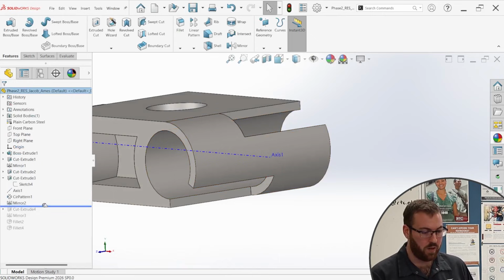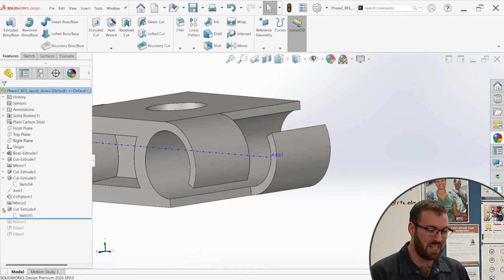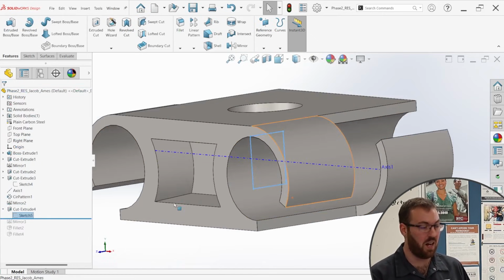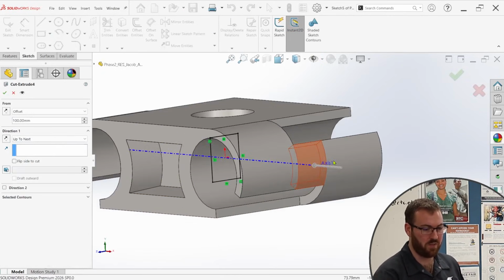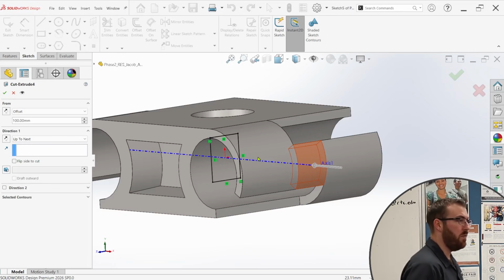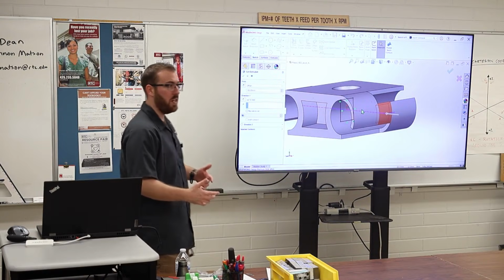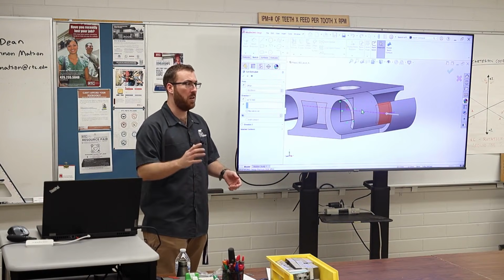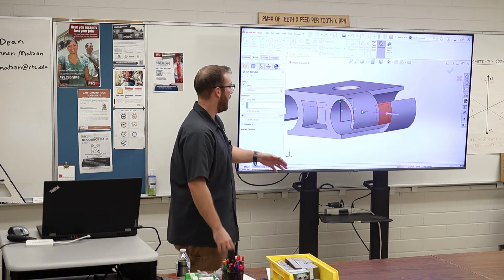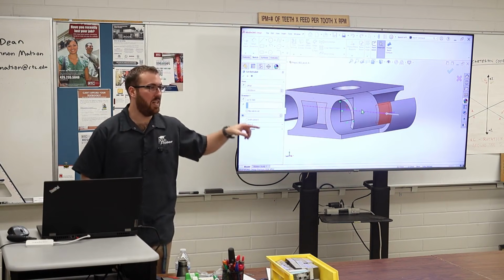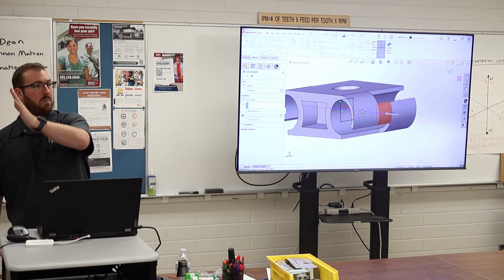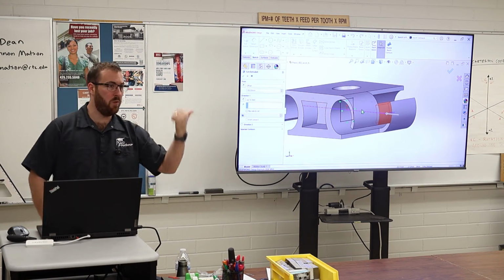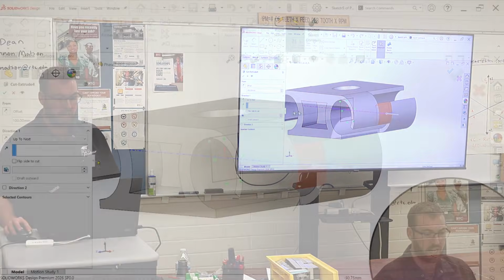With that being said, we create a simple cut extrude. I say simple, but the sketch is once again on the right plane. And if we take a look at the feature, this one's pretty clever. This uses an offset from condition. So we talked about from conditions already where we can choose where the feature starts. I just ripped the sketch out real quick and used an up to next end condition. So we basically bring the sketch way to the outside of the model and then tell it to cut back up through the next face.